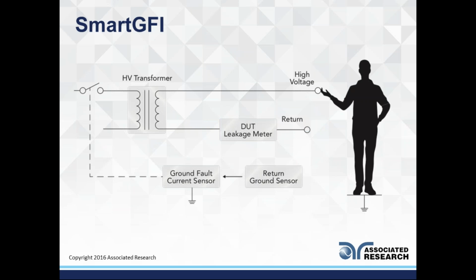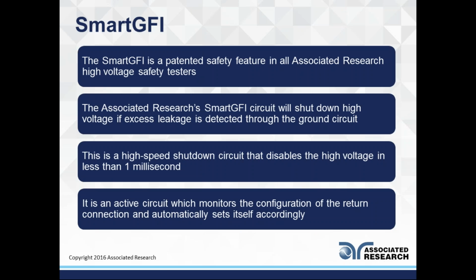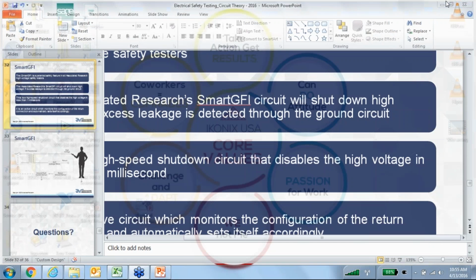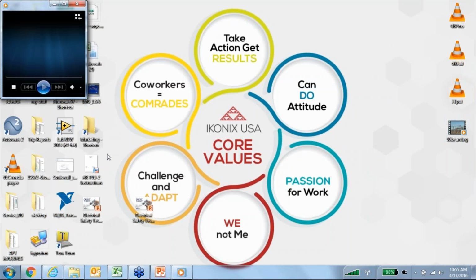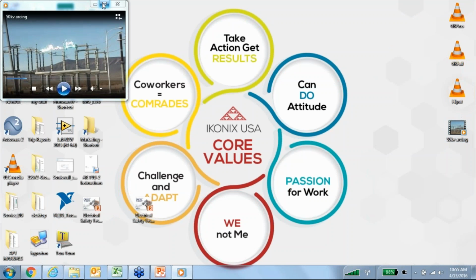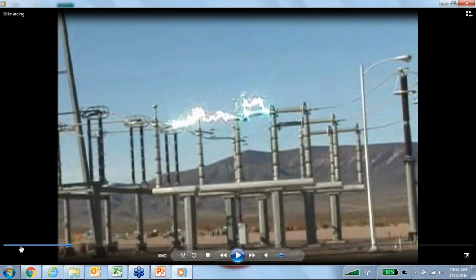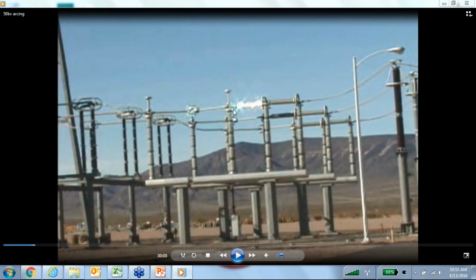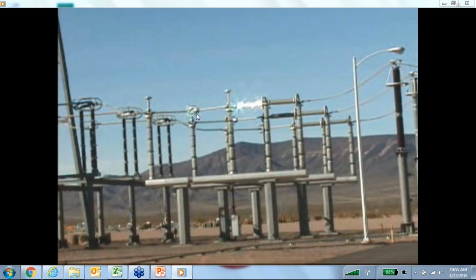Before, I wanted to show a video here. This is kind of an obnoxious example of arcing, but what we have here is your normal power plant where current is flowing through these conductive materials. Now, current wants to keep moving where it's going. It's found a path to ground, it's found highly conductive metal, so I'm going to flow on this. Now, when you open those and separate them, if that voltage is strong enough, if that electric field is strong enough, that current doesn't care.